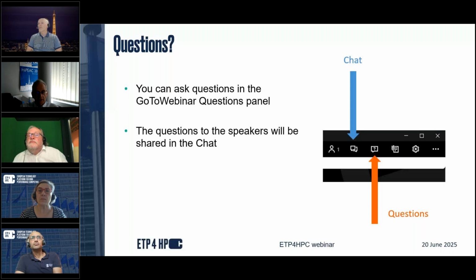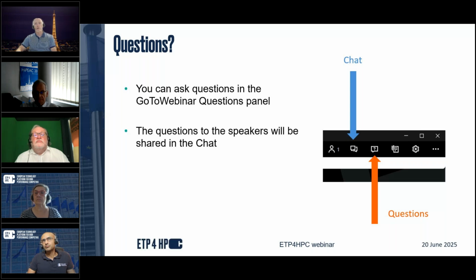Should I start, Mark? I think we both have things to say on this. Okay, so if we talk about acceleration, memory is a kind of acceleration. There's a bit of an explosion in terms of memory as well. HBM is certainly one kind that's very efficient for acceleration. I would say that it's less efficient on the compute side, but again, as we bring compute and acceleration into package, sharing high bandwidth memory and or DDR memory and or LPDDR memory, MRDIMMs, there's a lot of different kinds of memory coming. And this will also play a lot into how we segment, how we partition chiplet solutions.